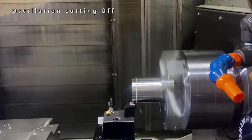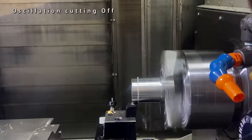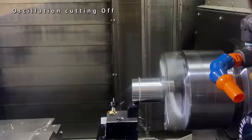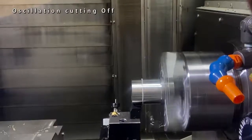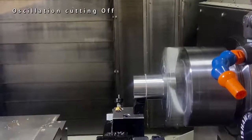Okay, this is OD roughing in lower turret. At first, turning without oscillation. Without oscillation, you can see long cutting chips. This is not good for automation and chip conveyor.